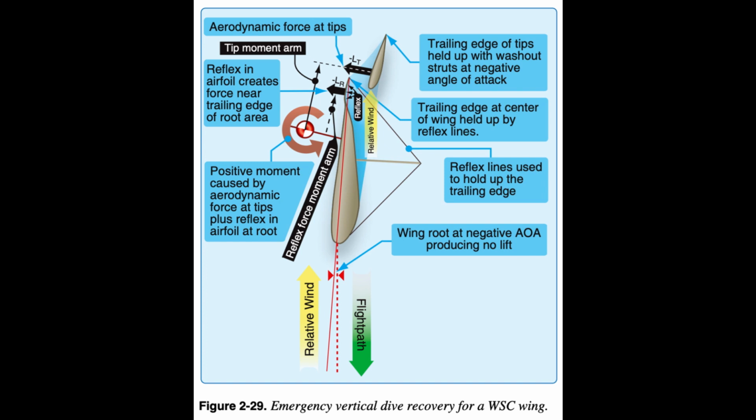Pitch moments summary. Overall, the amount of sweep, twist, specific airfoil design from root to the tip, and the carriage design determine the pitching moments of the WSC aircraft. Some have small pitching moments, some have greater pitching moments. Each WSC model is different, with a balance of these aerodynamic parameters to accomplish the specific mission for each unique carriage and wing combination.